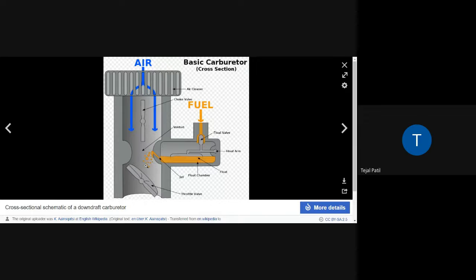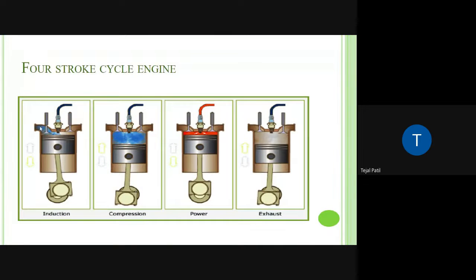That means in the combustion chamber you can't ensure that complete combustion takes place. So what will happen over here? Let's say you allow that diesel and air mixture to come inside; the diesel droplets are very big. When the spark plug sends the spark into this mixture, at certain sections, where there are small chambers, only where the droplet is small will the combustion start. If the droplet is bigger, the combustion will not start easily. It may need a very high temperature. Initially the combustion will start, but over a period of time the combustion process will start delaying.